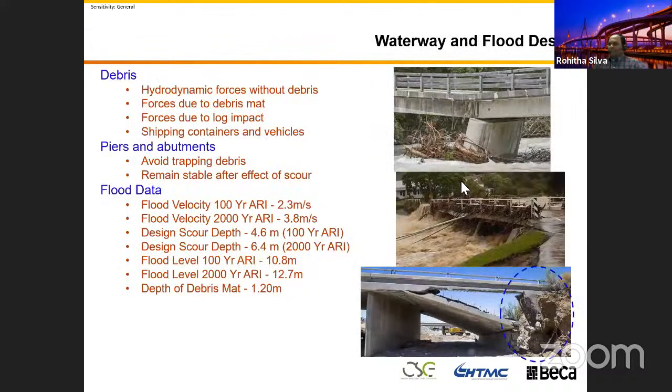And these are the pictures of what happened with the flood. I think you saw this on the abutment collapse, and you can see this bridge. There is no way you can stop all this debris, sometimes the log impacts and those things. You can see what happened to this bridge pier, and the bridge is already twisted and not in a serviceable condition. So when you design a bridge, especially in a waterway, you need to make sure that you design